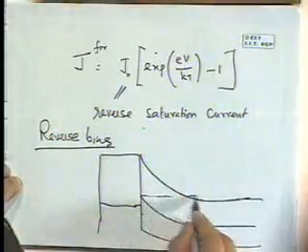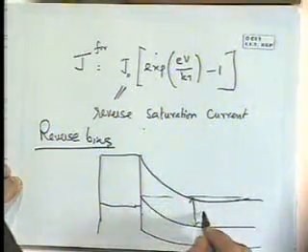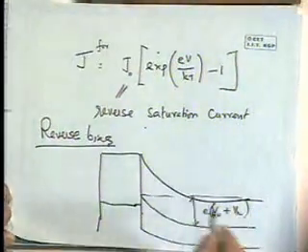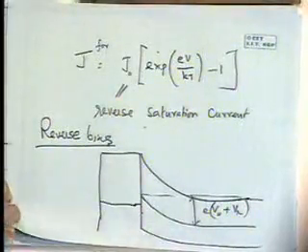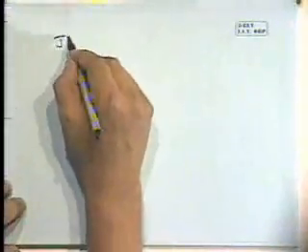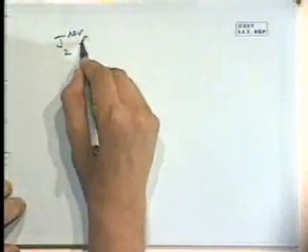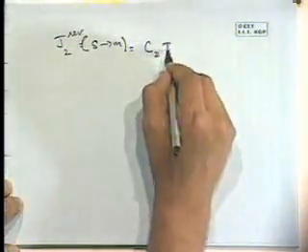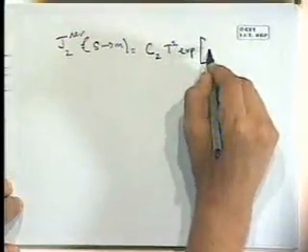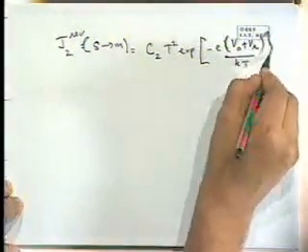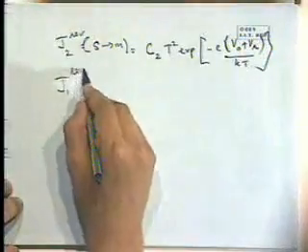Okay, basically now the barrier has added on, and we have eV0 plus the reverse bias. If we refer to reverse bias as V subscript R, then this is the situation. So again, now we have in the reverse case J2, which is for semiconductor to metal, is now C2 T squared exponential minus e(V0 plus VR) by kT. J1 hasn't changed.